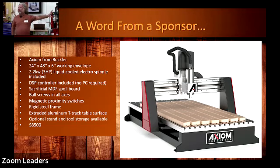The routers are basically air cooled, so we don't even really think about it so much. But for the higher powered machines, especially ones that are going to be running long periods of time, and there's other advantages to liquid cooled spindles, but that's what's being cooled. Does it translate to cooling the bit as well? No, not designed for that. You can still burn the bits.